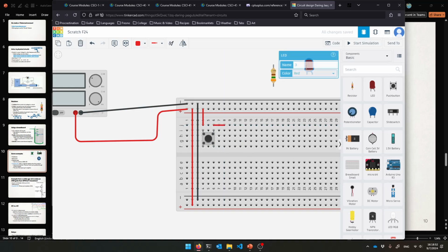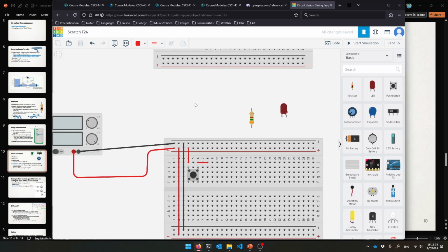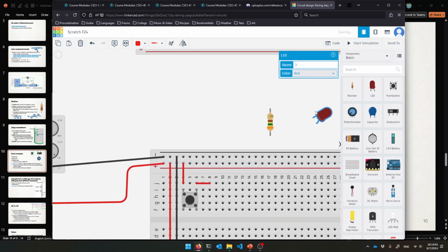And yeah, let's hook it straight in just to prove to you that instead of positive, resistor, LED, negative, you could have done positive, LED, resistor, negative, either order. So yeah, positive needs to go into the anode. So bam, we're lighting it up, coming in. If you press it down, it's jumping across, then we're coming in to the anode, out through the cathode, and then we need to go down to negative, but we want to resist it as well. So we'll go down through the resistor into negative.